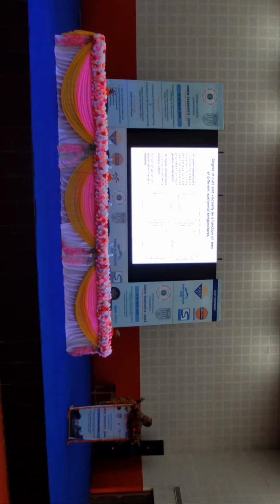So you can see that at lower temperature, viscosity remains constant for a long period due to slow reaction, before the attainment of resin gelation. But at a higher temperature, viscosity shows a biphasic nature. One is lowering of viscosity, the other is shooting up of viscosity. That's what is called biphasic in nature. Then it is applicable only until the gelation.